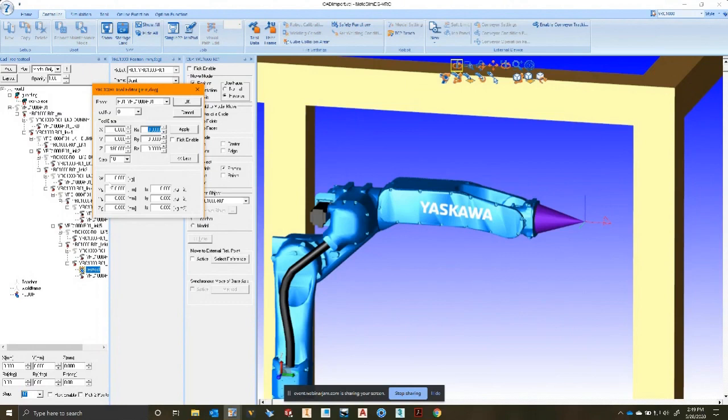They'll use a default parameter of the maximum tool weight that it can carry at a predefined distance for its center of mass. So in this case, this is a GP25, so it's going to assume it's carrying 25 kilograms right now at a predefined distance. I believe this is around 180 or so millimeters from the flange. And so these all may show 0, but they're actually not.